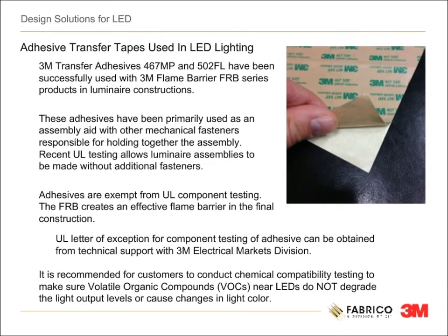One application for adhesive transfer tapes is applying the PSA onto the previously covered FRB series materials. The PSA aids in holding the FRB in place during its use, or simply as a third hand while either a mechanical fastener or assembly system is pinched in place. Since it is so thin, it helps in designing low-profile components with tight tolerances. This laminated assembly is easy to assemble, offers instant tack, and can help in eliminating fasteners while also sealing fixtures.